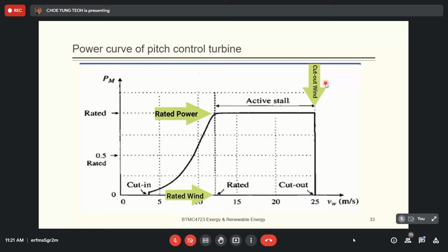So in that case, you need to stop your wind turbine from rotating, because your pitch control or stall control is not strong enough to reduce the lift force. So again, you need to stop the turbine from rotating. Then you apply the brake. Apply the brake, stop to 0. The speed must stop to 0.